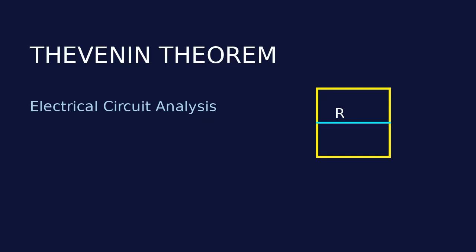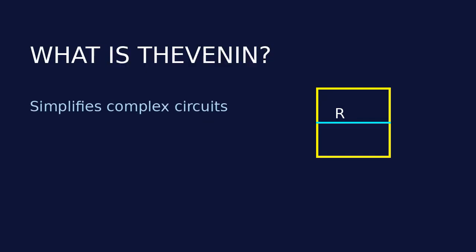Calculate the Thévenin voltage, the open circuit voltage between points A and B. With active sources, calculate the voltage using methods such as nodes or meshes. You can use the superposition theorem to analyze the effect of each of the two sources separately and add them.